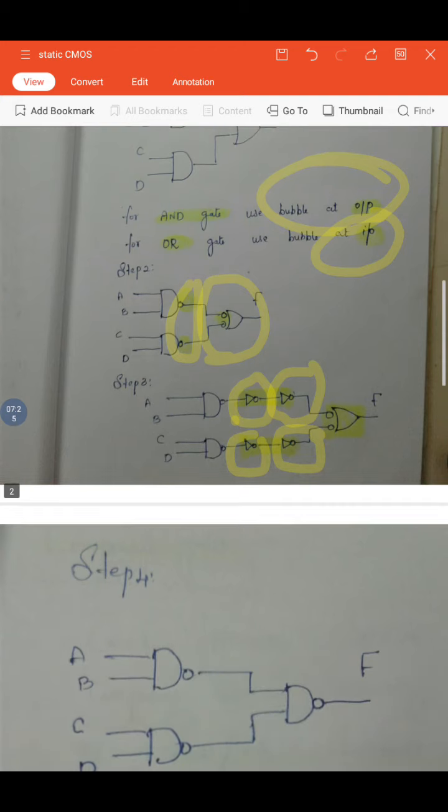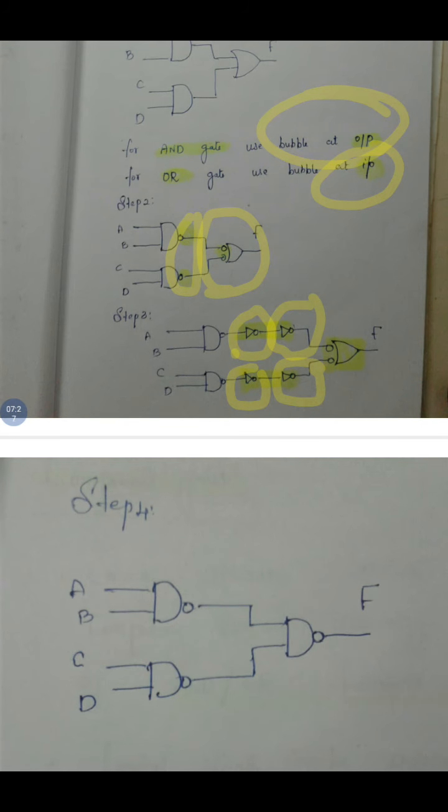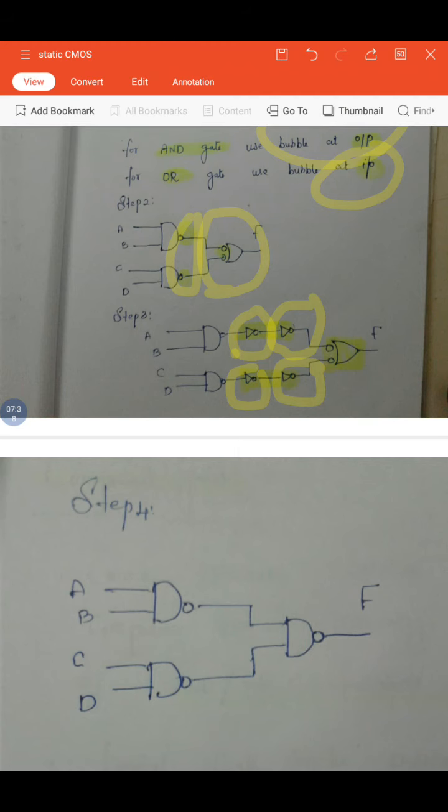So then, continuing, finally whenever we have two inverters sequentially connected, what will happen? For example, if I give 1 as my input, what will I get as the output? The inverter output would be 0, and then this 0 would be fed into the next inverter, so the next inverter would produce 1 again. Whatever value you fed, you get the same at the output side when you connect two inverters in series.